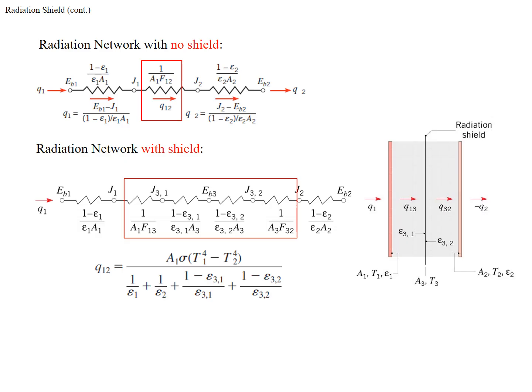You can see that all the areas in the denominator that would belong to the resistances are now factorized and show up in the numerator, because all the areas are considered to be the same for the case of two plane surfaces. These are not, for example, two cylinders, one inside another. Those areas are actually not the same.